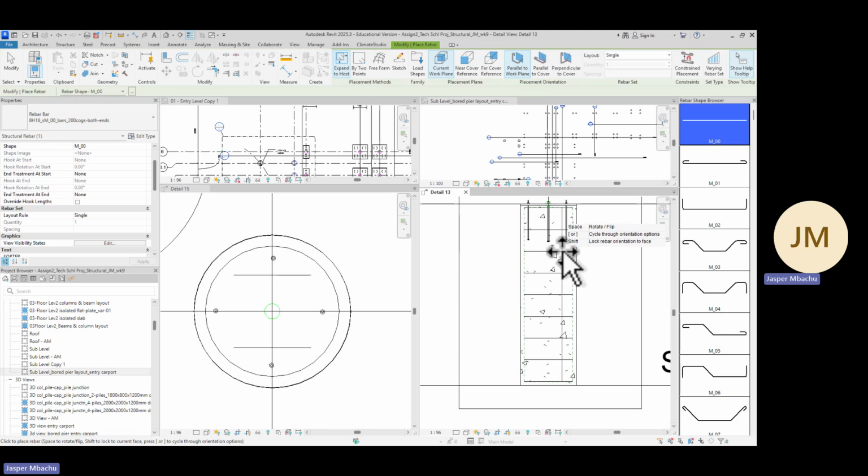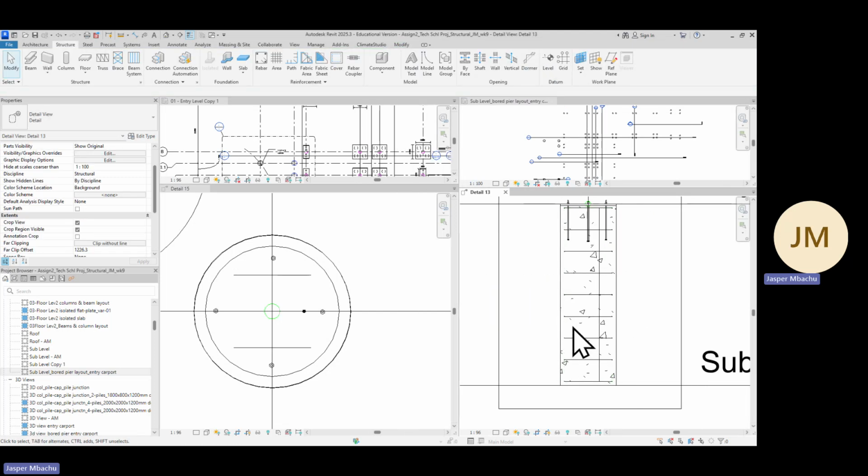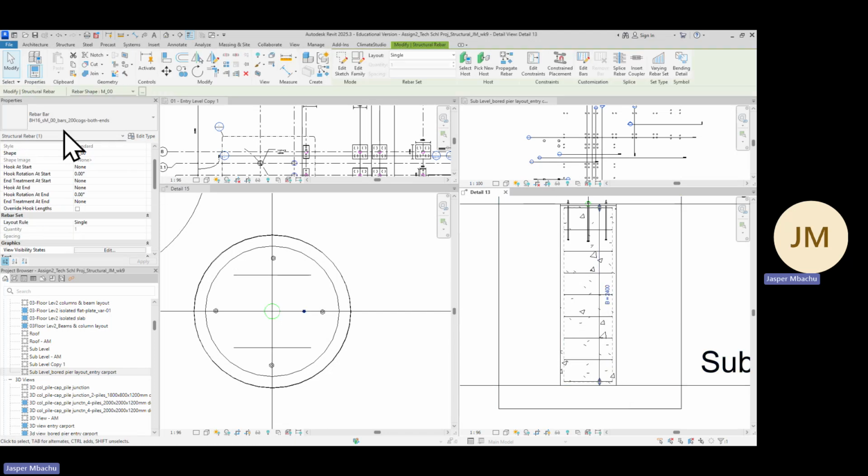Okay. Now it might be happening this way when you choose parallel to work plane and it shows a line. When you come back next time, it may not be the one. So at times you need to toggle and see the one that shows the position that you want. Then you place one instance of that. All right, place anywhere. Maybe place somewhere here. Escape.